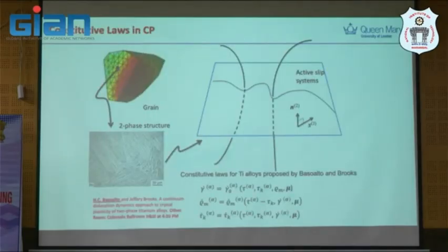Another thing is now more about the mechanical engineering side, where you may need to impose some solid mechanics. But this is not purely solid mechanics. What you see here is just a constitutive law that we impose into the crystal plasticity framework that we have. In one grain that we simulate, there should be about two structures when we see it at room temperature.